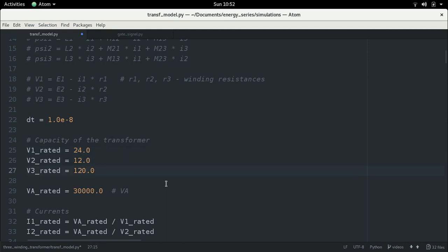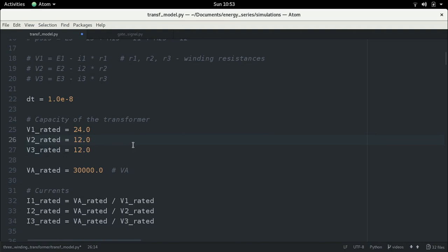And similarly, we can reduce this to 12 volts. That is, we can reduce the secondary winding to 12 volts. So what we are doing is we are stepping a 24 volt battery output to a 12 volt output, right? And this is quite normal. It does happen quite often. Matter of fact, this is usually what happens when you want to generate either a 5 volt or a 9 volt, right? You would choose a slightly higher winding ratio so that you can step down the voltage.